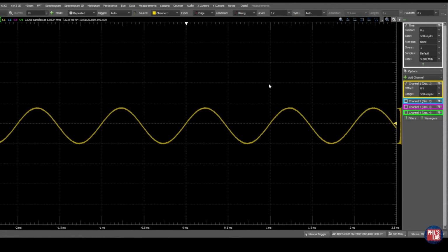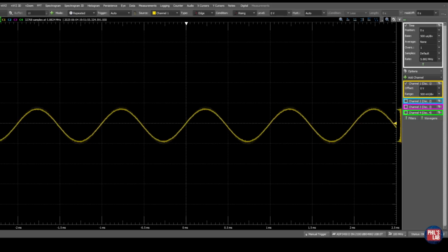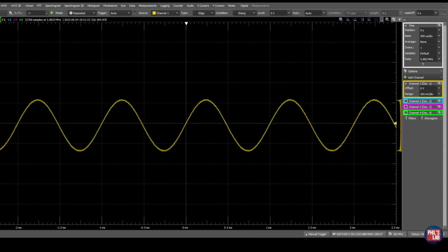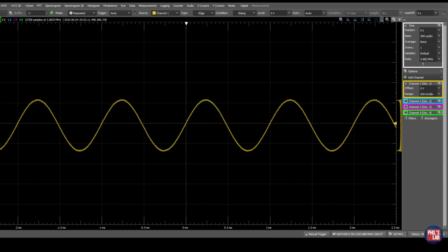Currently I have my release time set rather fast, so right to the minimum at about 1 millisecond. If I set my threshold to 0 dB, that is the compressor isn't engaged, if I then increase the threshold and then quickly release it, that time it takes to release or go back to the compressor being disengaged shows us the effect of the release time. So right now the release time is very quick. If I flick my threshold back to 0 dB, we can see amplitude jumps back to its maximum value very